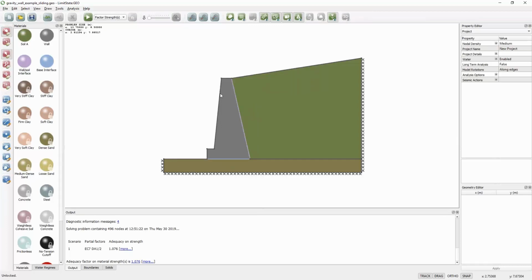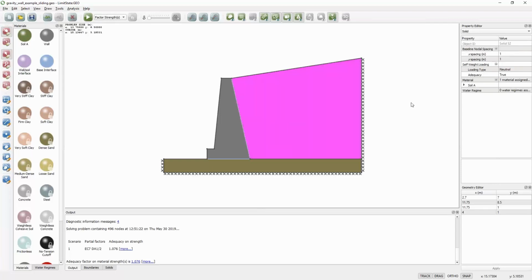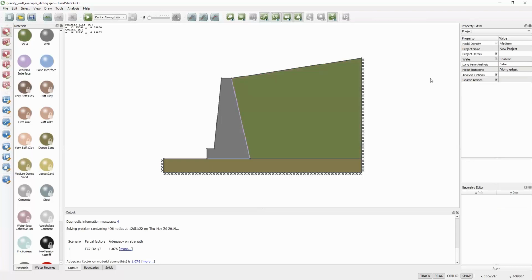Now, in order to apply the Eurocode, the software needs to know which materials or properties are favourable or unfavourable. So if I click on the body of soil here, its weight is going to be unfavourable. It's actually been set as neutral here, and neutral in the software doesn't have a strict Eurocode definition, it just means don't apply any factors. Strictly we'd set that to unfavourable. In fact, it doesn't make any difference for design approach 1 combination 2 because permanent unfavourable loads get factored by 1 anyway, so we would get exactly the same result.